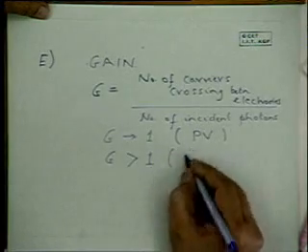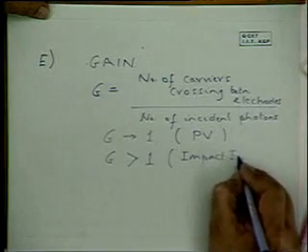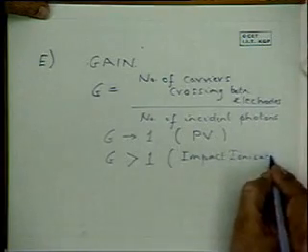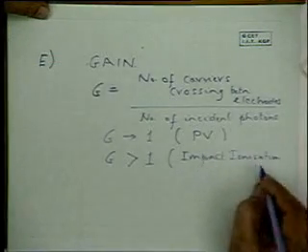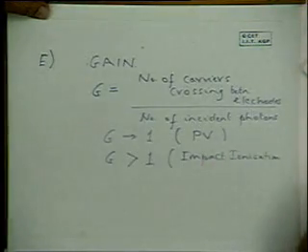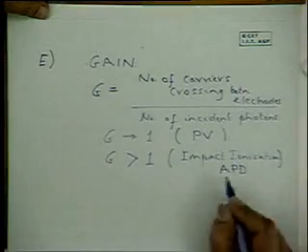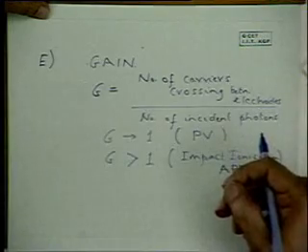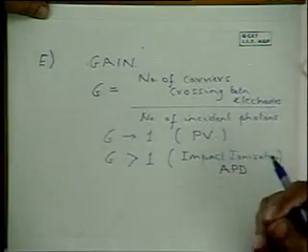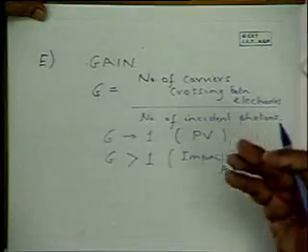Obviously, if you have high field phenomena like impact ionization, followed by avalanche multiplication. So for avalanche photodiodes, we can have gain which is greater than 1. That means one photon gives rise to an electron-hole pair. Then that electron, due to high field, can create additional electrons, so that finally we have, for one photon, many more than 1 electrons and holes collected. So that is one case.